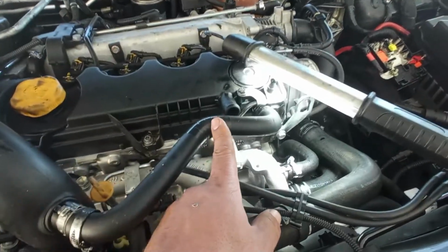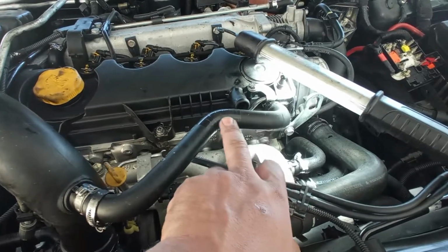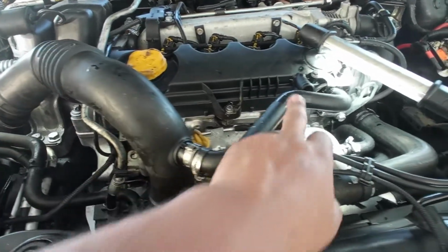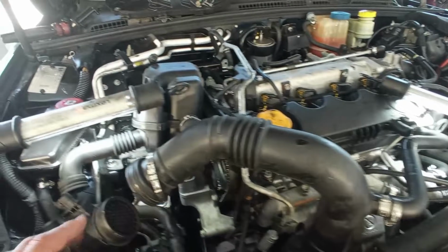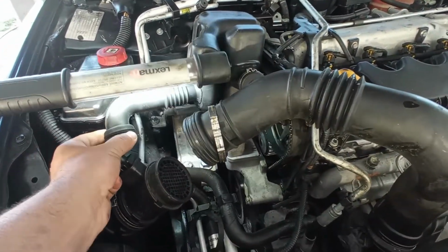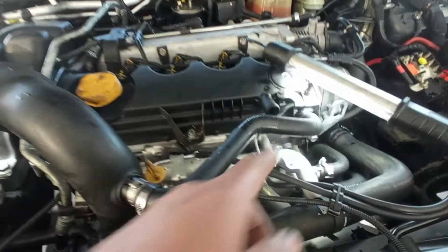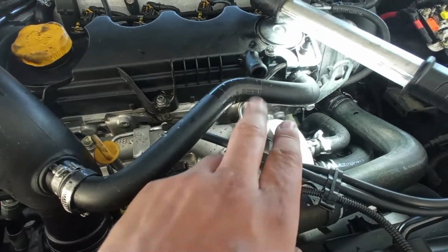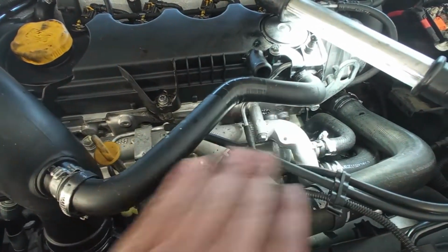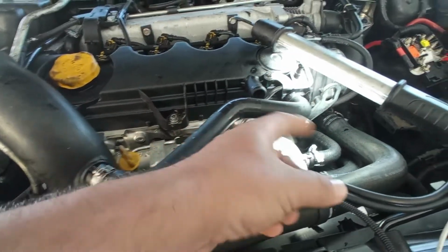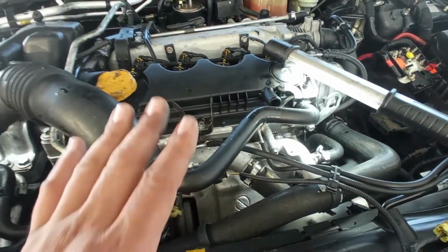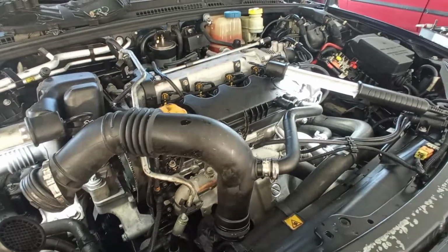Number two, a big tear here on this breather pipe, which means again that air is sucked through this pipe and goes to the engine without being measured through the mass airflow meter. So that's two things, okay? So this one is very easy to repair. You just put there a clamp, normal or not, and over here I just put here some duct tape so I can do my testing without replacing right away this pipe. By the way, this pipe is available, only this section from factory, but it is a little bit expensive and the customer has a lot on his plate right now. So let's just do the testing here as it is.